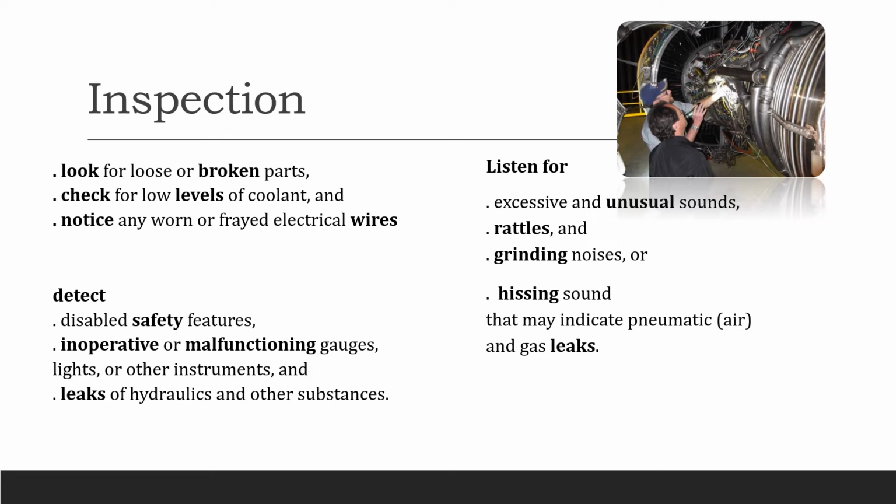So these are all called the routine inspection that you do for hydraulics and other substances, trying to find the leaks. It's so important in order for the system to run. The system can run with one leak, two leaks, fine, but it's better to run without leaks. So you will check for all of that. And you're going to listen, because systems always create noise.